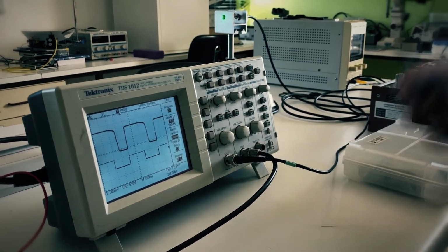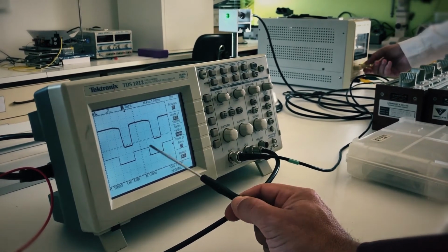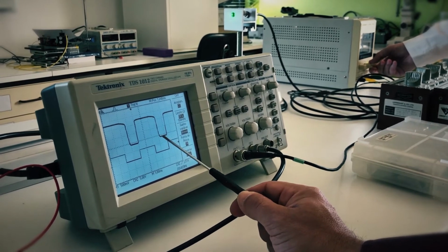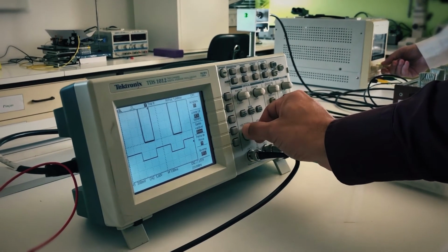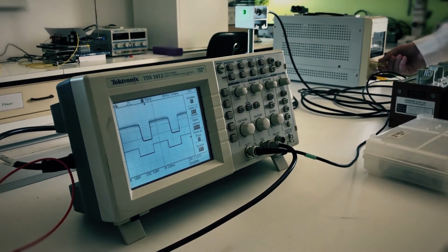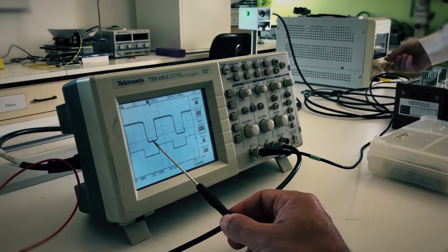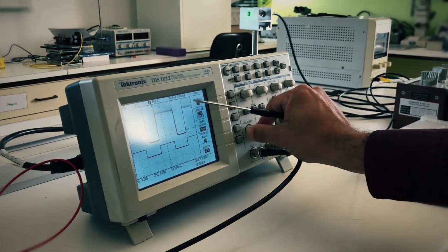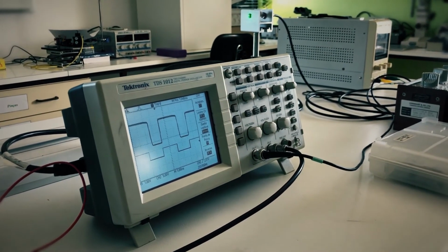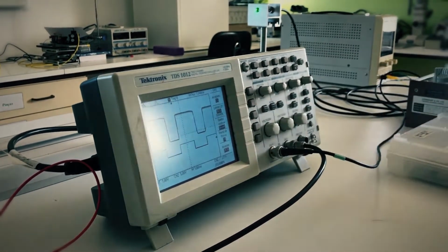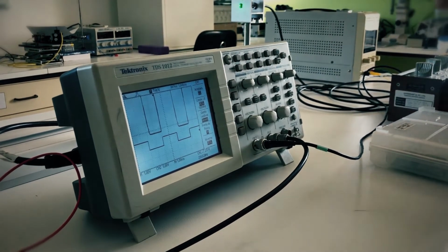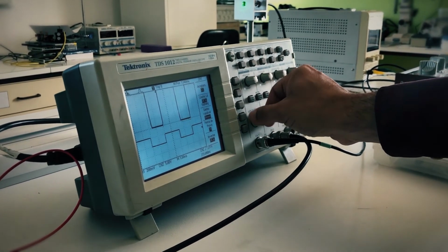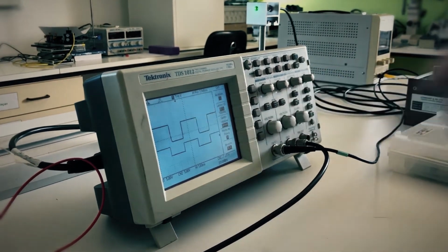Imagine you had a photodiode that had this response profile due to high internal resistance, or with a very extensive intrinsic region. It is possible to attenuate the effect of the slow carriers' response by increasing the reverse bias modulus, which means increasing the electric field intensity. This should be enough to provide the slow carriers with enough acceleration to improve the fall time of the device, meaning that the current output won't be carried out for so long after the light stimulus is removed.